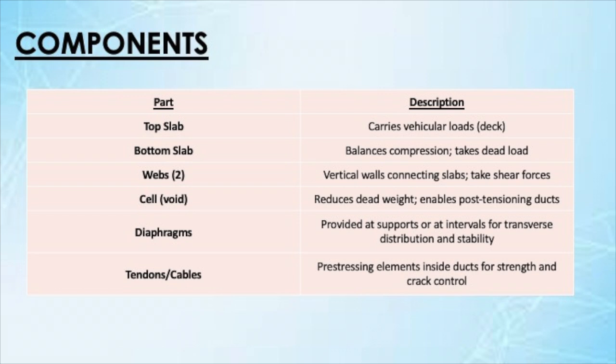Diaphragms are provided at the supports and at intervals for transverse distribution and stability. And tendons or cables are applied in pre-stressed concrete. Pre-stressing elements inside ducts provide strength and crack control.